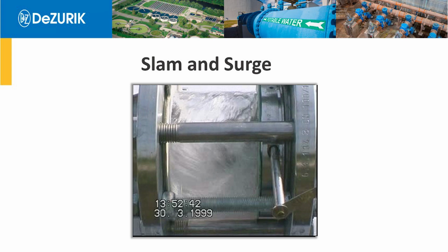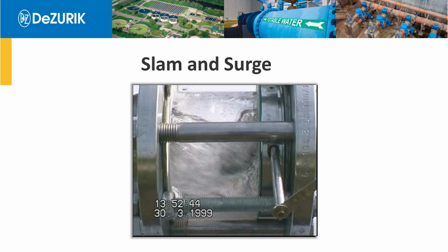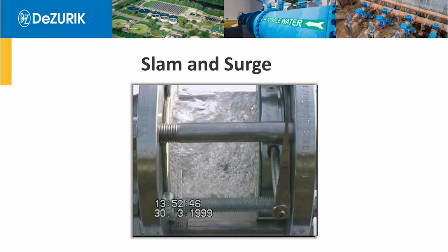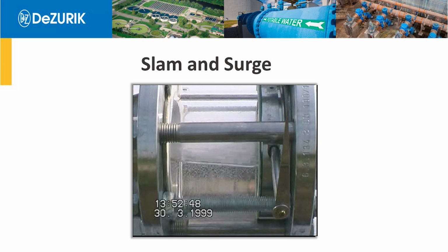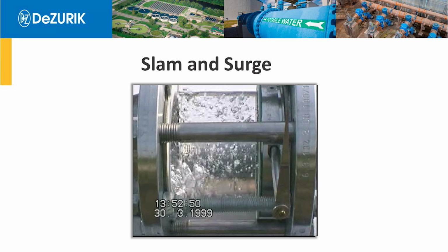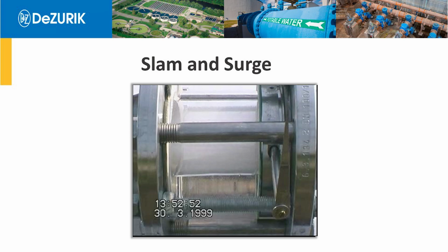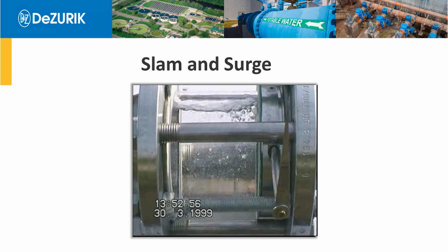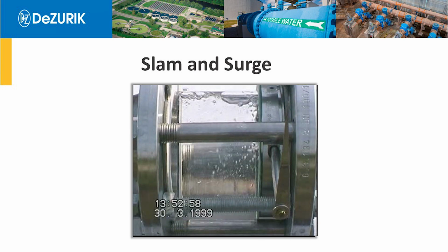That's the turning off of the pump. Here's the check valve slam. Now you see the surge wave theory. Upsurge, downsurge. Upsurge, downsurge. And if you would time that, that's one critical period between the upsurge and the downsurge.